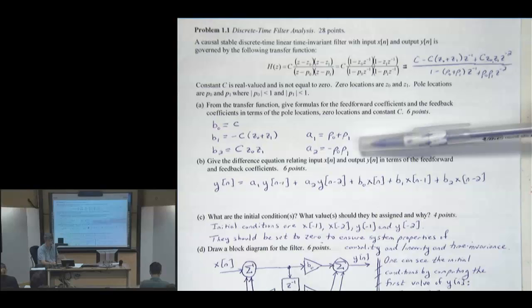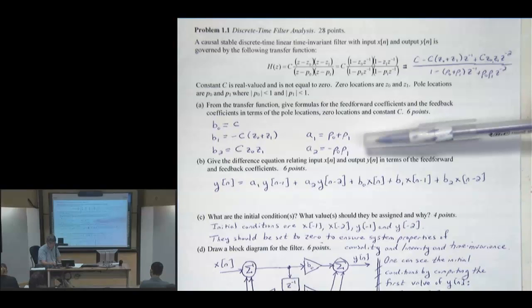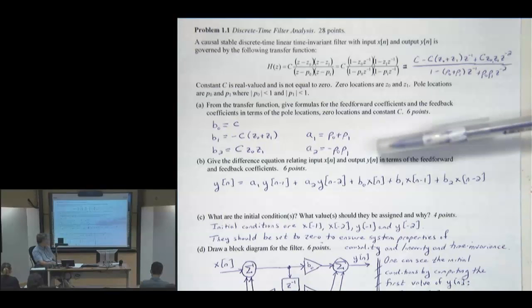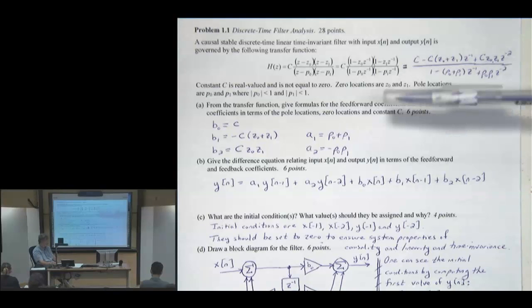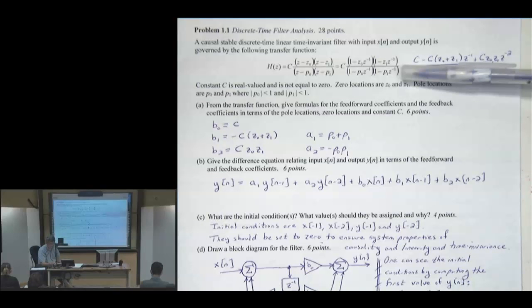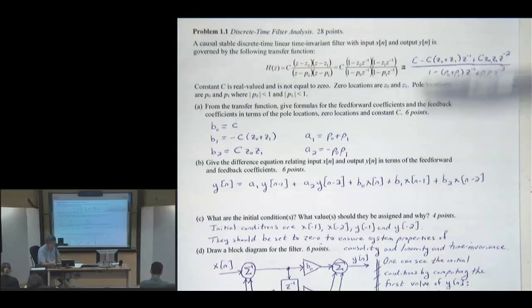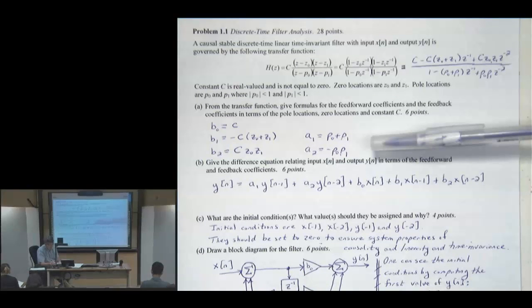We get a distortion in the pole location, which can lead to instability when implemented. We tend to expand this only for biquads just to control the amount of distortion in the actual pole locations due to this expansion. Again, the filter design algorithms return poles, zeros and gain, and this unfactored form is good for implementation as a biquad or in biquads.